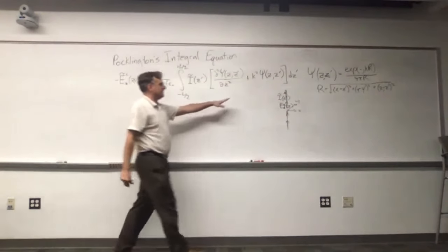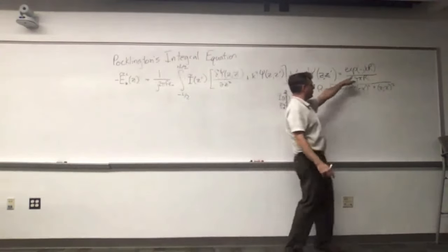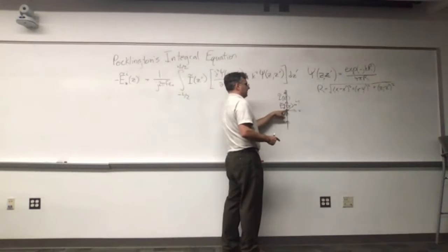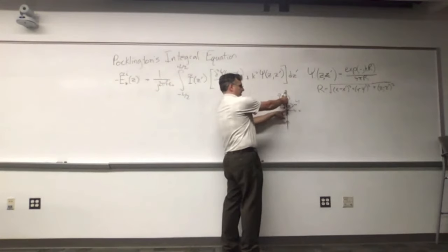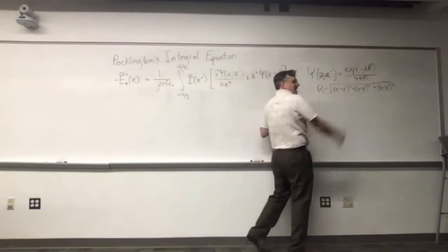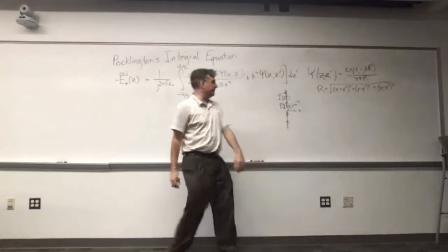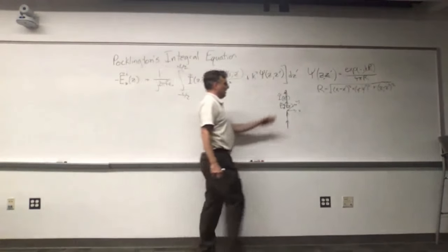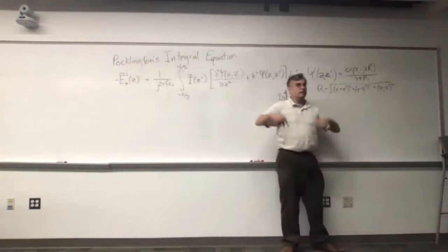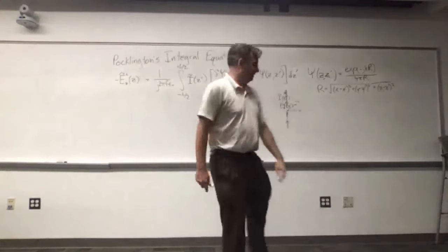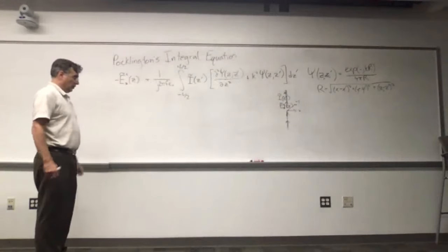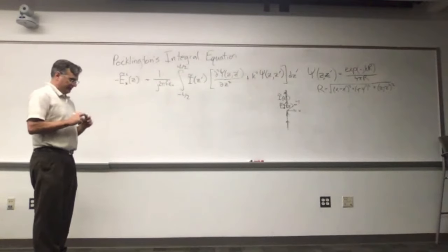And we can see kind of your standard propagation terms. Okay, it makes sense that the field here is going to be influenced by the current here. And there's an exp to the minus jkr, where k is the free space wave number. There's, of course, a frequency dependence here. The influence is going to fall off 1 over r, just like any other field expression. So how would you go about solving this?